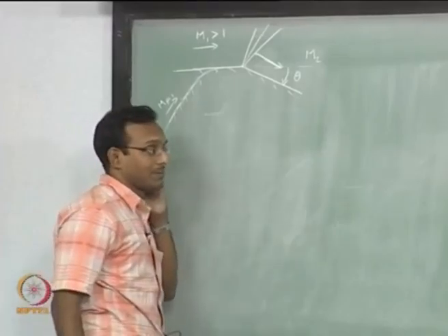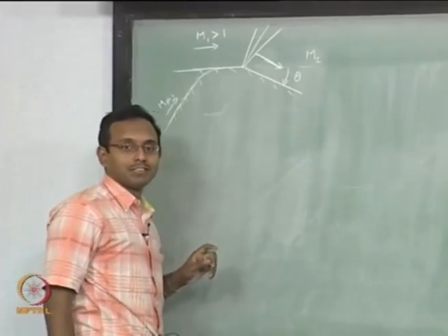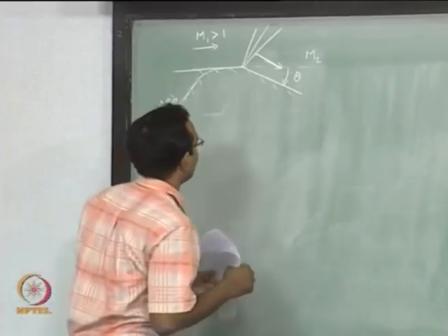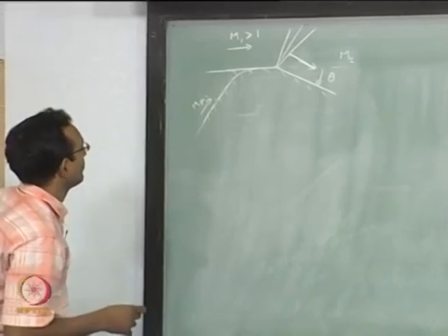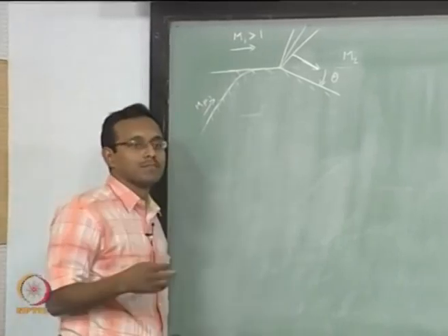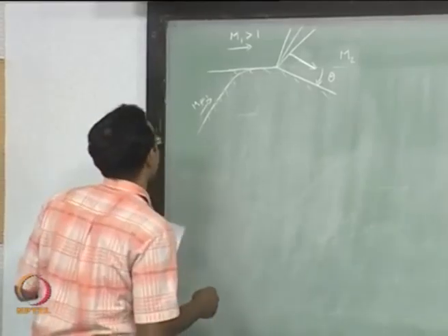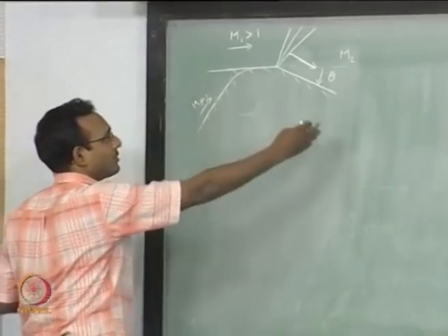And by the way, the Prandtl-Meyer function is a monotonic function. It is not going to go up and down, it just keeps on increasing. That is one more important thing you should know. But as it goes to very high Mach numbers, the number does not change much, it is going to asymptote to a particular value. But this is how you have to think about it.